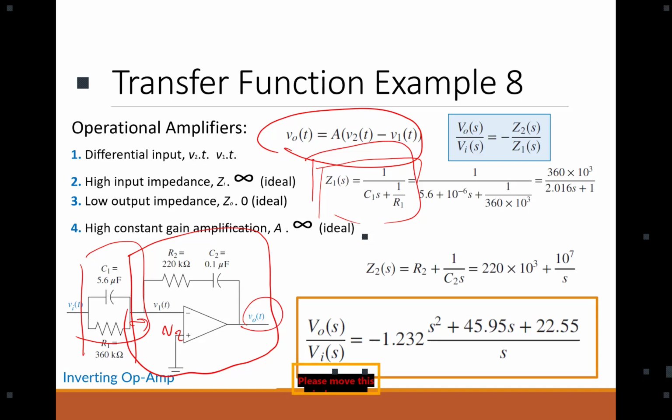So whatever voltage you have here, you have here. Are we good? So this one doesn't drain any current. Current here is 0. Meaning whatever current is passing here is going to go through this Z2 impedance to the output. Now you have simple KVL. Make sense?